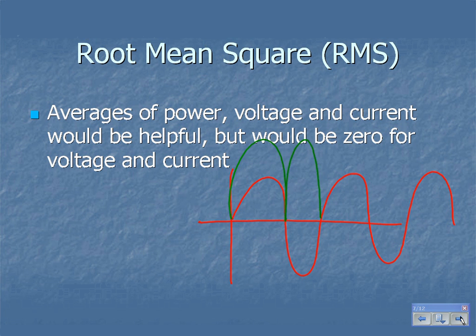Then I take the average. Now I have everything positive, so I take the average, which would be something up here. Well, that's not truly the average because I squared everything. So I'll take the square root of my average, and it gives me a new number that is now a numerical value that is roughly the average if everything were positive, okay? It's called the root mean squared value, and it's a good way of giving you an average even though the average would truly be 0, okay?